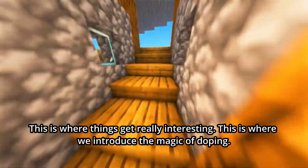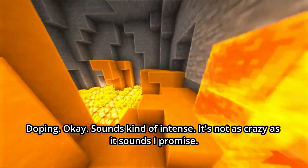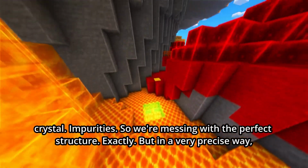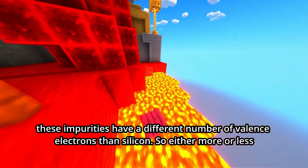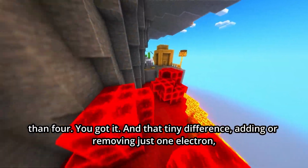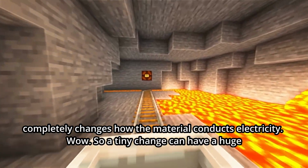This is where things get really interesting. This is where we introduce the magic of doping. Doping. Okay, sounds kind of intense. It's not as crazy as it sounds, I promise. It's basically a very controlled way of adding tiny amounts of impurities into the pure silicon crystal. Impurities. So we're messing with the perfect structure. Exactly, but in a very precise way. These impurities have a different number of valence electrons than silicon. So either more or less than 4. You got it. And that tiny difference, adding or removing just 1 electron, completely changes how the material conducts electricity. Wow, so a tiny change can have a huge impact.